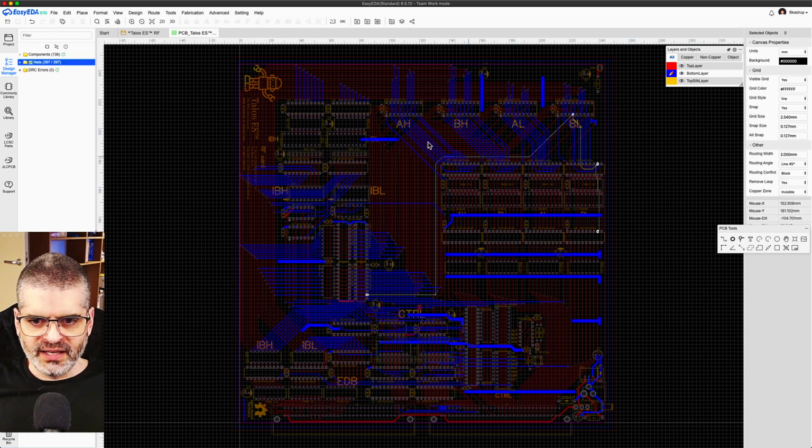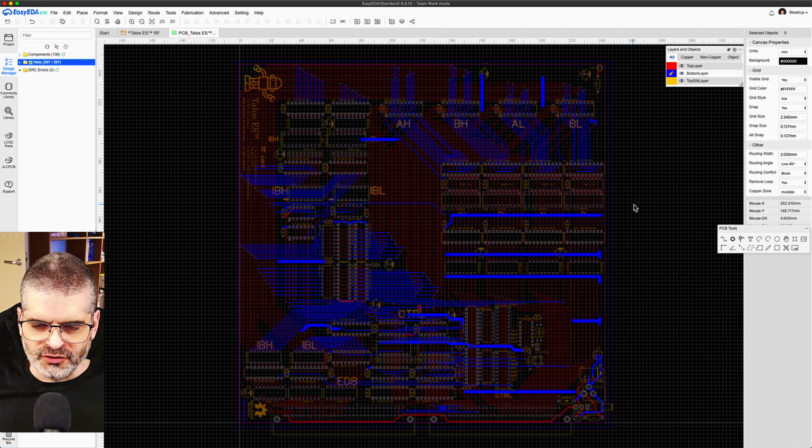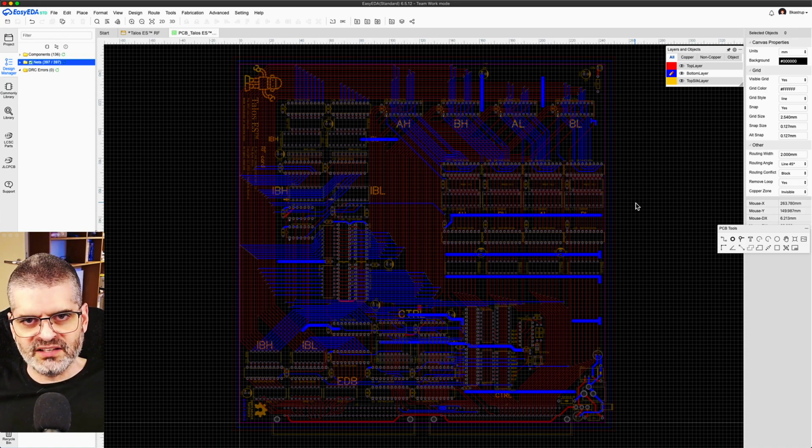And don't be afraid of diagonal lines, because some people look at these old retro boards from the 70s and 80s, and you will not find anything diagonal there. Why was that? Well, it's because they didn't have CAD tools like we have today. And it's much easier and faster to get a first routing that works, that connects everything, if you stick to only horizontal in one layer and only vertical in the other layer. You have a much higher chance of succeeding first time. And that's why they did that.